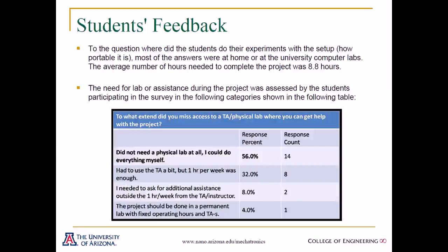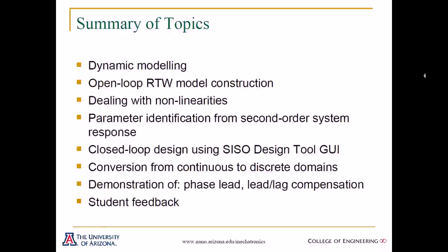In conclusion, I would like to recap the main topics that were covered in this presentation. We discussed the development of a dynamic model, the design of an open-loop Real-Time Windows Target model, dealing with nonlinearities and eliminating them using feedback linearization, identifying the parameters of the system, designing a closed-loop controller using the SISO design tool, conversion from continuous to discrete domains, and demonstration of a phase lead and lead-lag compensation. Finally, the presentation reviewed some of the student feedback from this project.